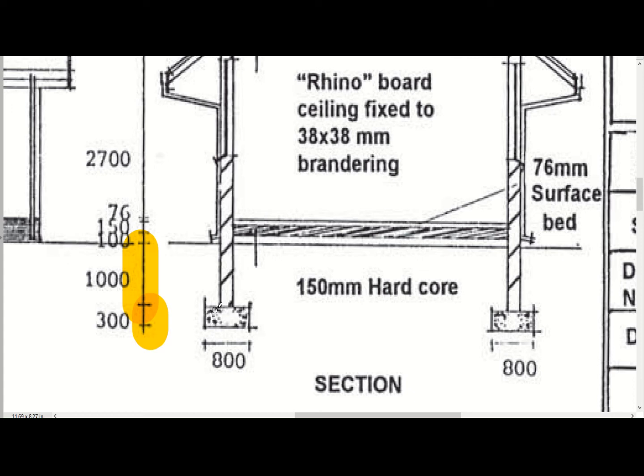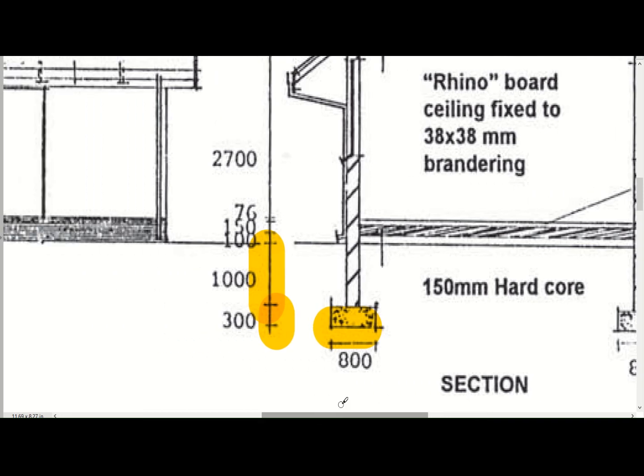Whenever you do your measurement in your bills of quantities, your excavations will be in cubes and not in meters like what we're measuring now. Then you will times it with your total length, that's the 36 meters that you measured, times 800 mils times your height. So it's always length times your breadth times your height. That's usually the way to stagger it. It just makes life easy whenever someone else takes up your measurement. Okay, so that's more or less how the measurement works.